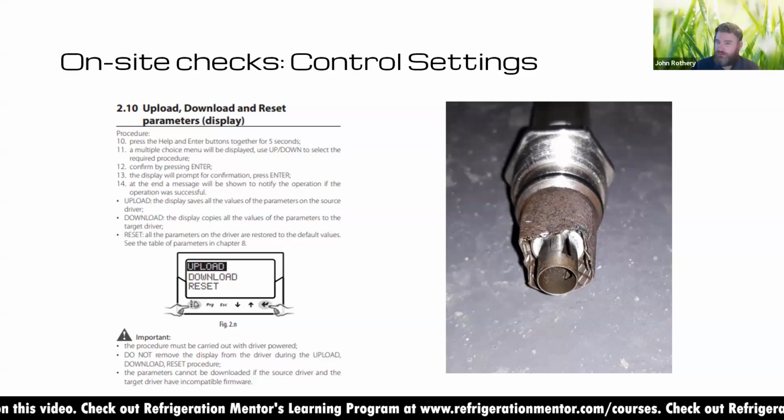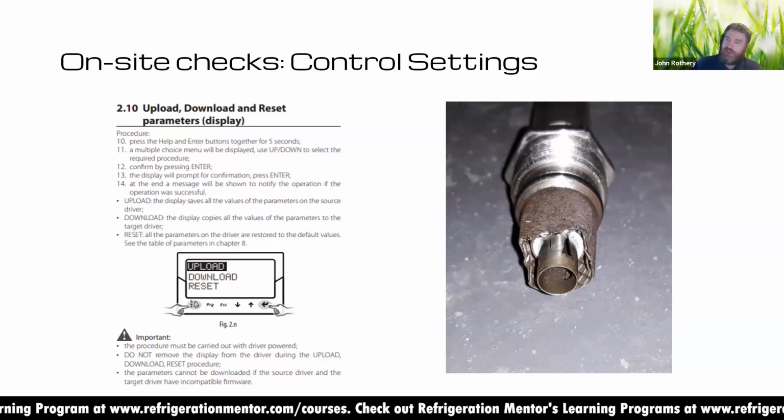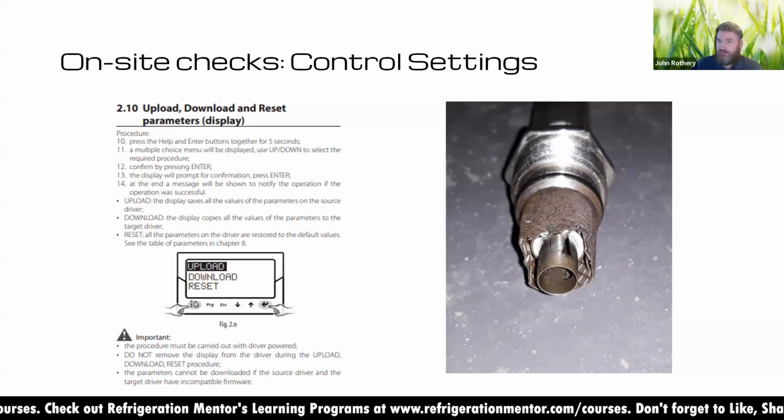Yeah. And that text to the side just shows the ability you've got with, I think it's the Carel EVD Evo, where you have an interchangeable display. You can upload the settings to the display and have that as a backup. So if that valve driver ever fails, you can take the display off, put it back on, and download the settings, so it saves you a lot of time. Equally, if you've got another pack on site with a second display, you can upload it and transfer it across. As long as it's the same system and commissioned the same, it can save you a lot of time and headache. So, love that.